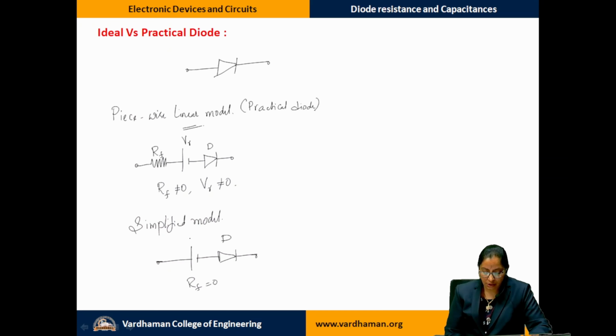So this is the diode direction, this is your barrier. This is the simplified equivalent model, according to which the VI characteristics also get altered. So let us plot for the piecewise linear model. As it is a practical case, the VI characteristics is going to be the same. This is your forward current in the range of milliamperes, and in reverse bias condition, reverse current, which is in the range of microamperes.